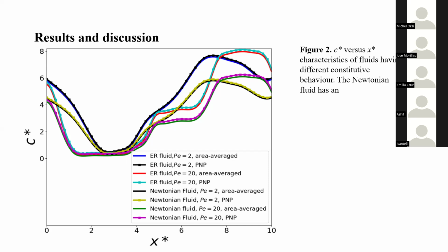0.000064. To depict the electrorheology of the fluid, we take eta equals 0.1 Pascal second, sigma star equals 5 into 10 to the power 8. And we also take tau E equals C E squared, where C is 2.5 into 10 to the power minus 10 Newton per volt squared, and E1 equals 4 kilovolt per millimeter. The physical configuration consists of flow between two infinite flat plates, one fixed and raised to a potential, the other being grounded and moving with constant speed.